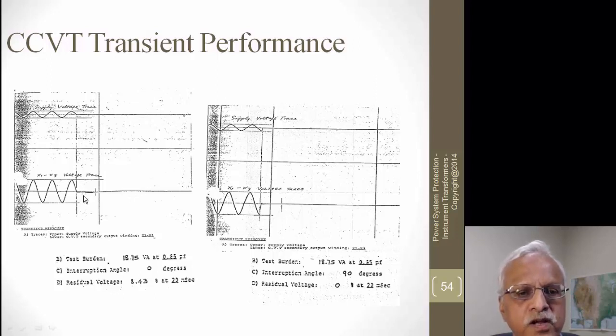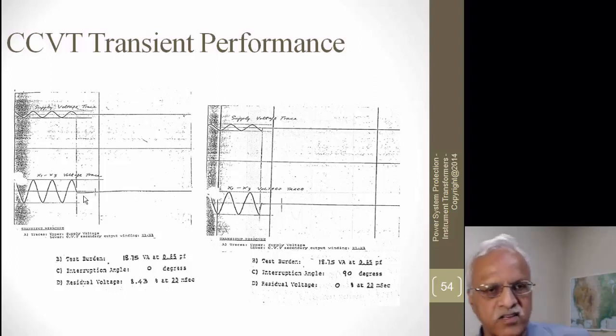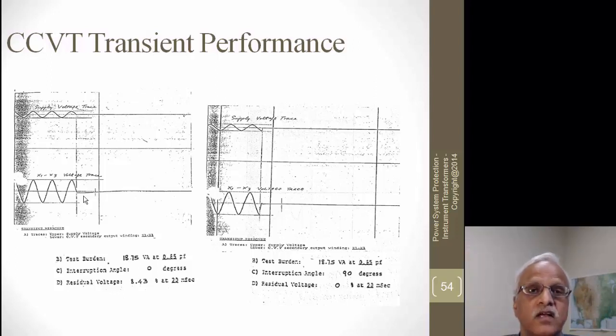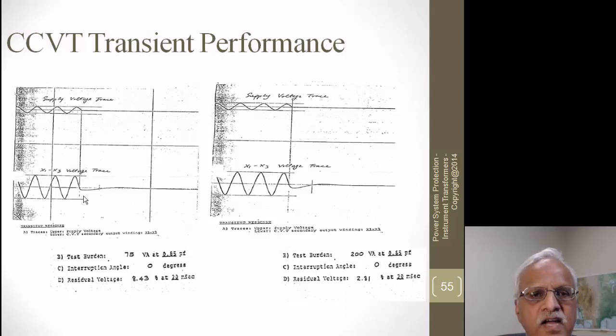This is shown here, and what it does is, you have a sinusoidal voltage and a sinusoidal current. If the voltage is not sinusoidal, it's a decaying quantity, and the current is very high, which is still reproduced very well by the current transformer, you might have a wrong direction detection or wrong impedance measurement on the relay side. So it has an effect on transmission line relays. So you take measures, you know how this performs, and take corrective actions.